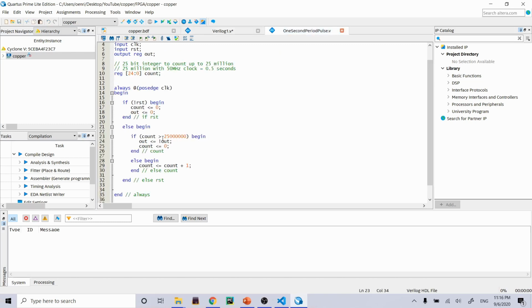So here I defined a constant in the code as just a number, 25 million. In all honesty, I cheated quite a good bit by doing this. In fair practice, you would want to define something more like count is a 25-bit number. So instead of just 25 million, you'd want to actually define a number of bits. That's the first number, and an apostrophe. That's what tells it how many bits. And now you define how you want to tell it the number. You have a few options.